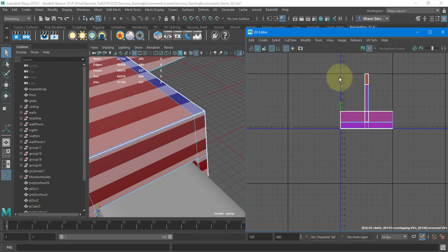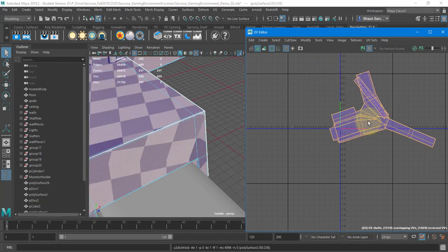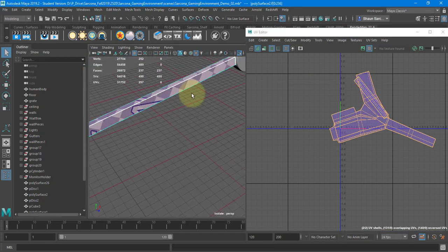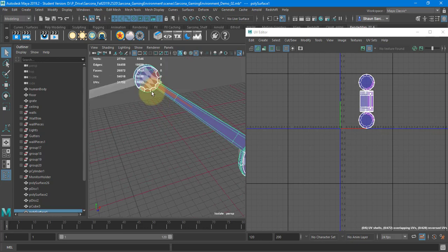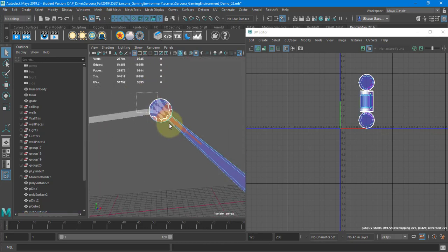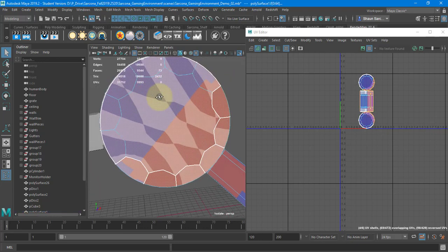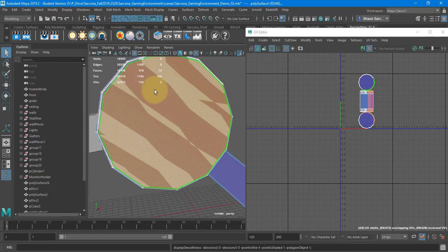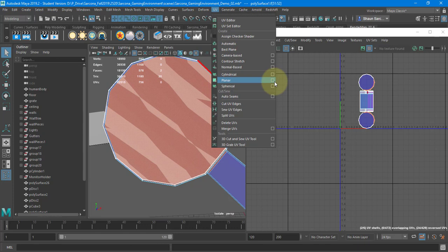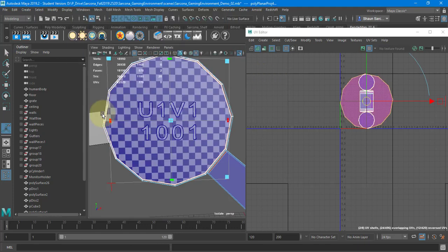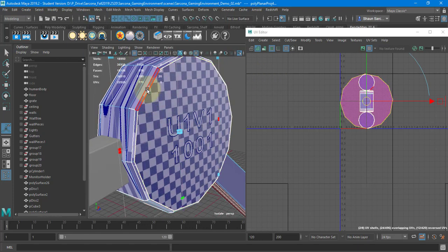Okay, now I'm not going to do the whole thing because this will take me a little bit longer, but then I would go through and unfold it, and then I would get that shape. Then I would do the same thing to this piece, breaking it up into individual pieces. So I would treat this cylinder as a planar right here. So let me grab these, and I would go into planar, set this to the Z direction, and that's perfect. And then grab these pieces here.